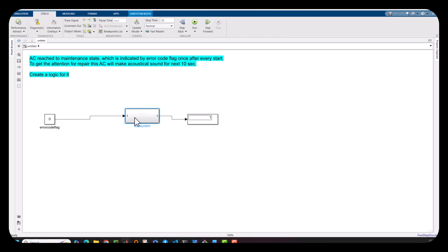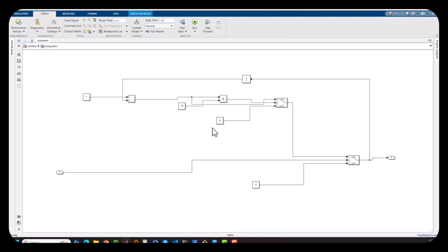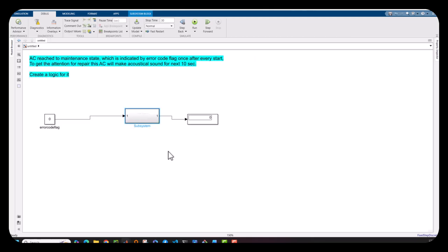So this is again simply enabling the subsystem with signal propagation. So let's start with 0. After 2 steps, again make it 1. The counter started. After 1 value, it got 0. So again the counter is 0 over here. It means this logic also will not work. So enable subsystem, trigger subsystem, or the signal with the switch is not working. So what could be another solution that we can do?